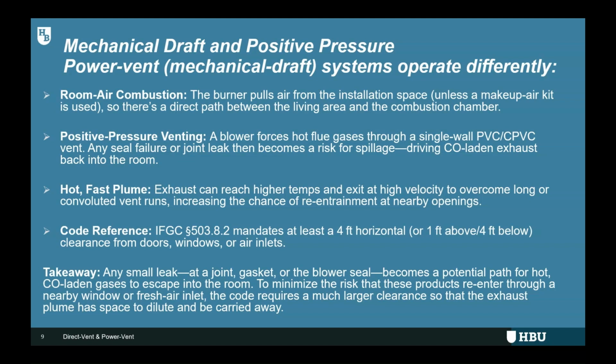Third, hot, fast plume. The blower in a power vent system often results in the exhaust gases exiting the vent terminal at a higher temperature and velocity. This increases the potential for those gases to be drawn back into the building through the nearby windows or fresh air inlets, a phenomenon known as re-entrainment.